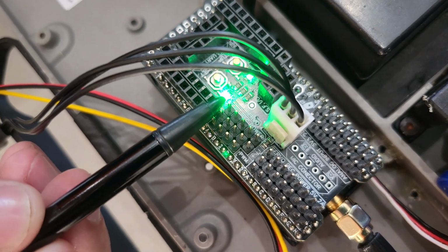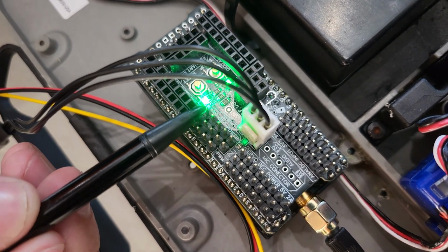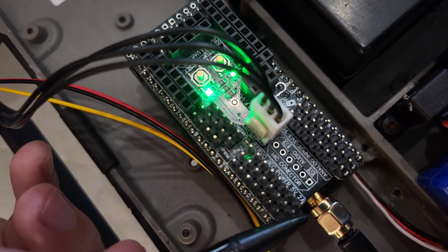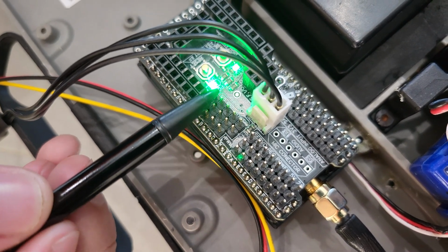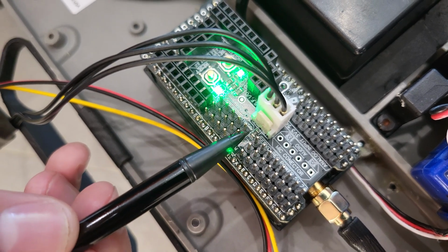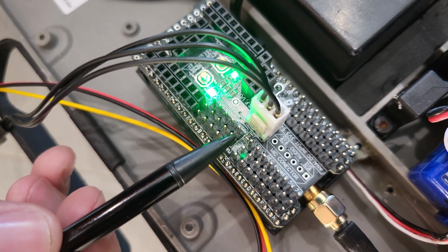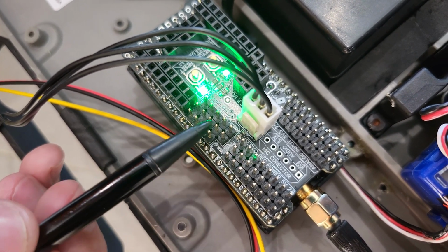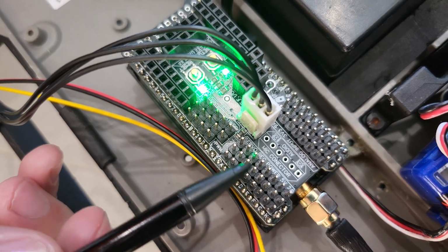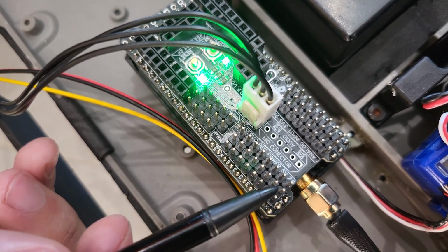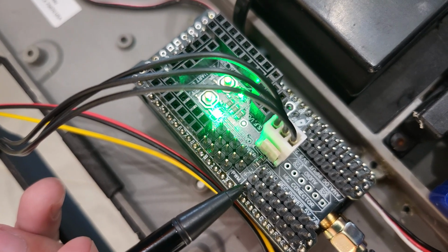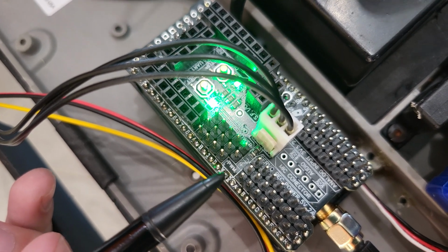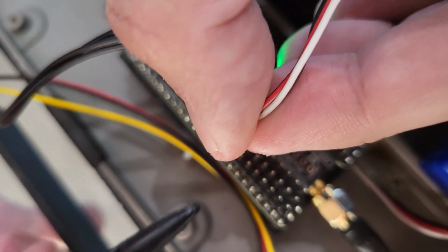These terminals shown in the video are designed to power the servos, and there is a smaller bank of terminals and it is powered by the ESC. Since the ESC is still not connected from the safety reasons, we are going to use the larger bank of terminals to power our steering servo. We are going to connect our steering servo to servo output A.